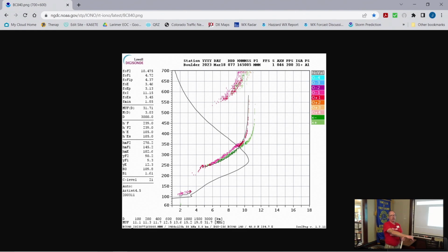He's one of the stations I test against because I can pull his receiver up online and see it and hear it. And I will transmit from my house in Fort Collins with an NVIS antenna as I watch this. And when 40 meters is open, for instance, he will hear me just fine on 10 watts. When this goes away, I can crank up to 100 and I don't make a blip on his screen. So it's very dramatic and abrupt.